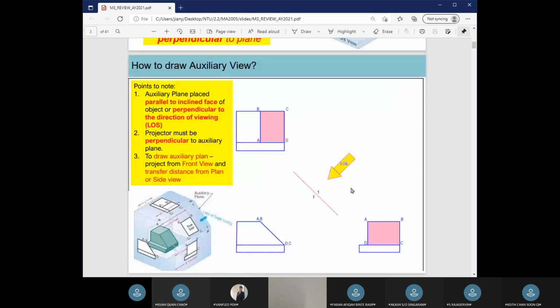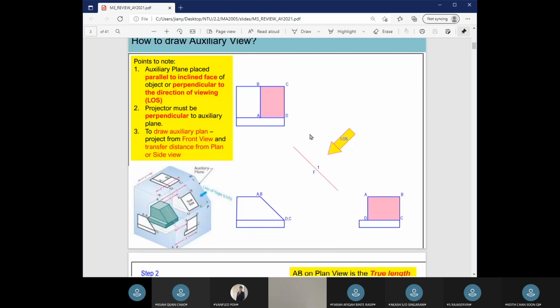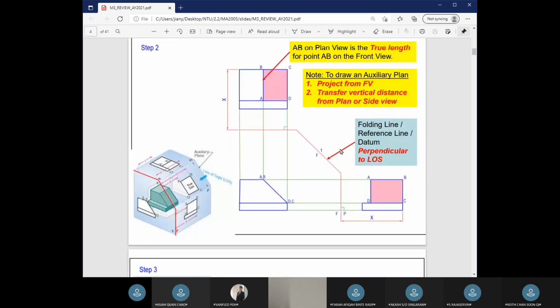So okay, first step, what do you do? You replicate the different plane views first: the side view, the front view, and the right side view. As you can see, it will look something like this for this simple shape. Now the second step. For this shape, they want you to project along a 45-degree angle. So for the first step, you draw a 45-degree line. Next step.